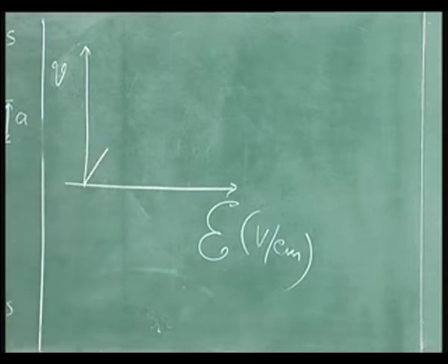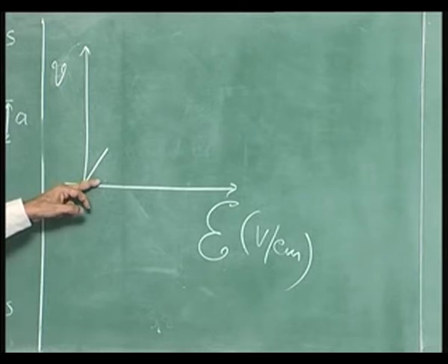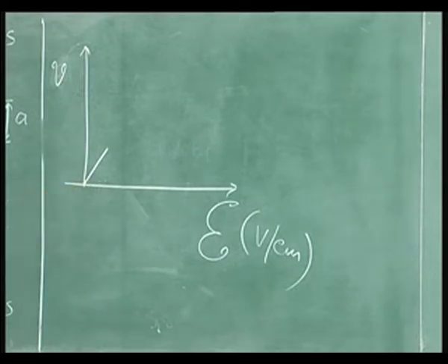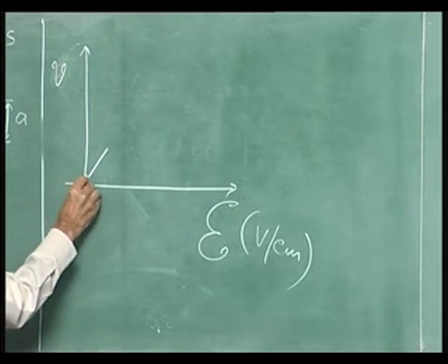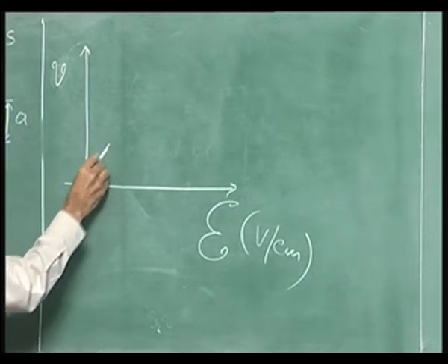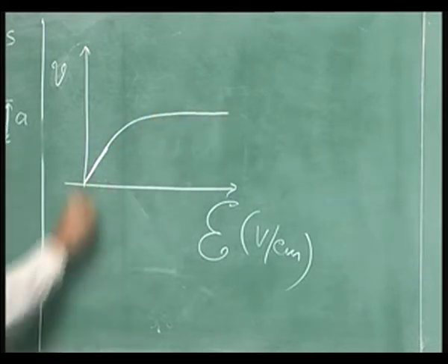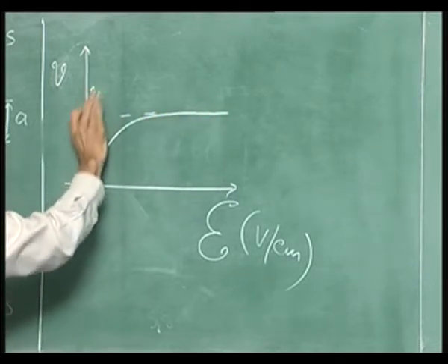It goes on linearly, and we have used that it is going to remain linear right through the electric field, right up to the pinch off point, and then we gave up and said okay, that pinches off, that is the condition. But actually in silicon it goes up like this, and saturates. So, you have got a saturation velocity.